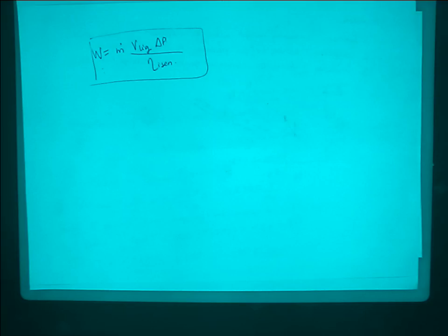Okay. Talking about the efficiency. How do we get the efficiency? Is there a chart? Like the isentropic efficiency. How do they calculate the efficiency before, when we are designing? Is there a formula? Yes, the problem is that you can get that efficiency, but you will need to know the temperature at the inlet and the temperature at the outlet. So you actually will need to measure that and then obtain the isentropic efficiency.